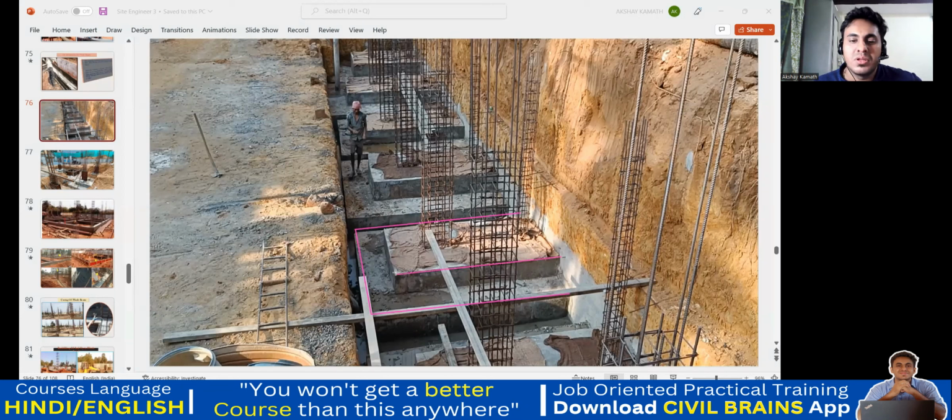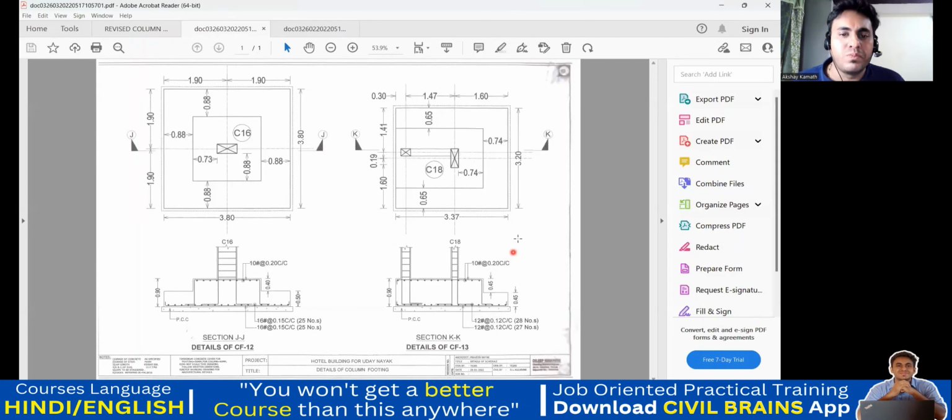Similarly on the top also the same thing. This length, this breadth, and this length. You add all the 3. Here there won't be any shuttering because it is attached to the wall. That portion of shuttering you have to take out. I'll do one for you. This only we'll try to do. Quickly, I'll not do it in Excel. Here itself, I'll do that.